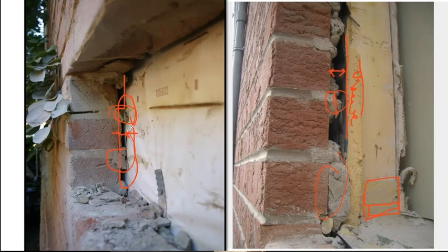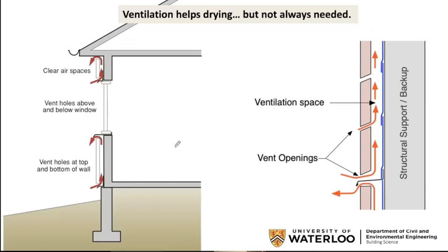And when it does that pressure, suddenly nail holes, such as the nail holes created by the masonry anchoring device called a masonry tie, become potential leakage spots. Or any other staple hole or nail hole or whatever, suddenly could leak water if you have a blockage. So this is the complicated aspect of cavities.